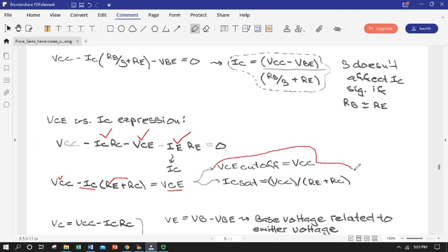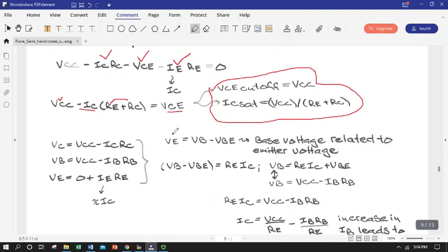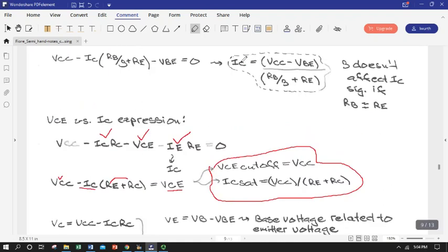So here's my load line. That made it pretty easy. And if I want to get my Q operating point, all I do is plug this expression in for I sub C, and I can solve for my VCE with a little bit of math and get my Q point. I might just calculate a number for I sub C from here and plug it in if I need to.